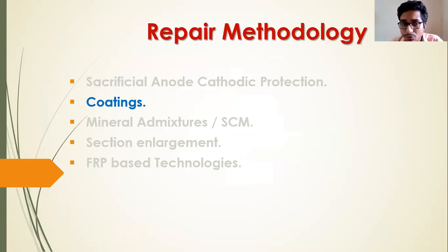And coating is something that in most cases, before giving the coating, the surface preparation is quite important, because if the surface preparation is not good, there won't be any good bonding with the coating. Coating may be anything. It may be paint, it may be different types of laminates, it may be patching work or whatever. So the surface preparation before coating is quite important to achieve a good bond.